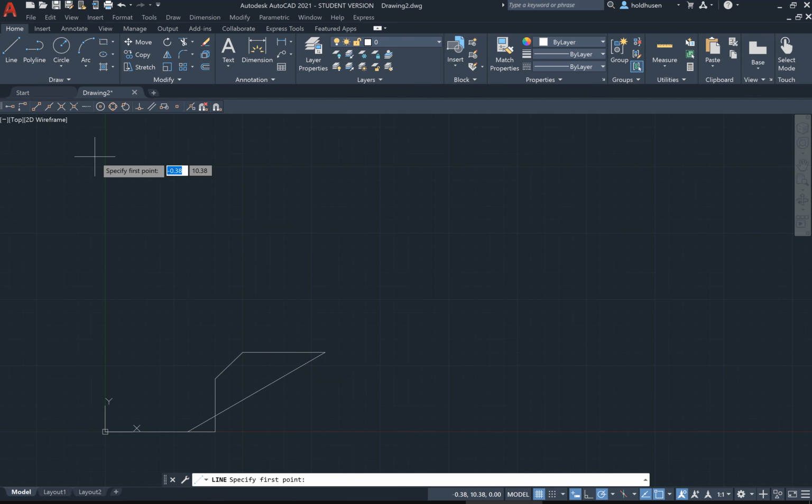I started a line. Polar coordinates will still be relative because that's the default with my dynamic input. But what you do instead is you say, how long of a line do I want? So let's say I want a 3-inch line, and I want an angle 30 degrees from the horizontal. So I do the less than sign, and then I can type in 30 degrees.